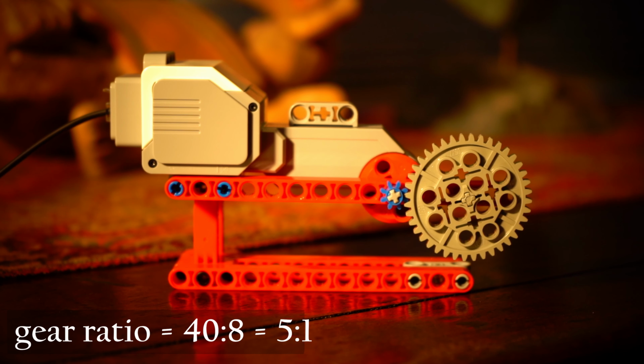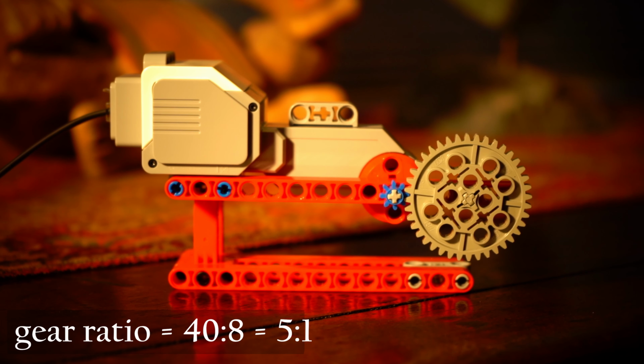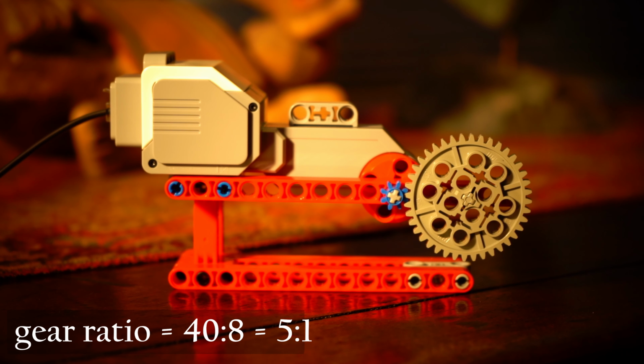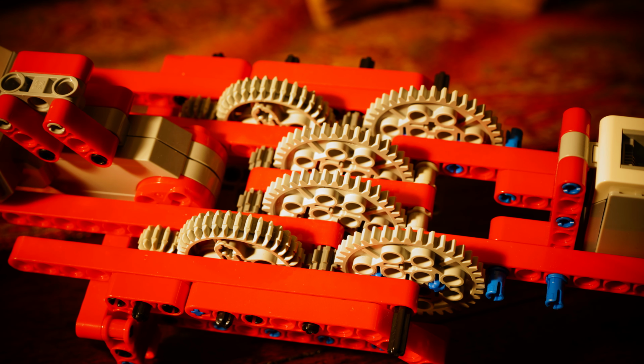In other words, the driver gear will turn 5 times faster than the driven gear, but the driven gear will have approximately 5 times more torque and the ability to rotate, lift, or otherwise move greater mass than the driver gear. If sufficient torque cannot be achieved through a simple gear train, a compound gear train can be utilized.